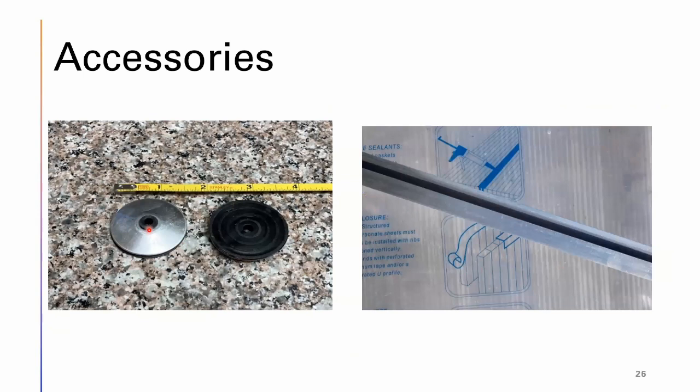Okay, when you're looking at YouTube channels, one thing you'll notice, if you look at Bigelow Brook Farms, they have a popular YouTube channel for domes. They just use standard tin roofing screws into wood through their polycarbonate. That voids the warranty. What happens is you have localized stress that results in premature yellowing and cracking, and it would void the 10-year warranty. You have to use wide screws.